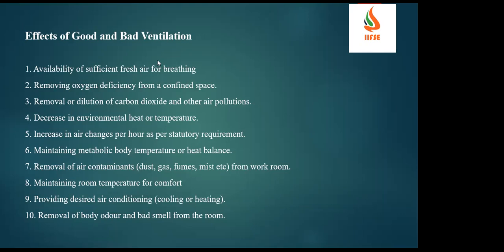If I'm not wrong, I think per hour, 6 or 6 to 7 times. I think the total volume of the room has to be changed. For example, if I say the air volume is 10 cubic meters, then minimum 6 to 7 times, if I'm not wrong, the air change has to happen. That is a good portion.